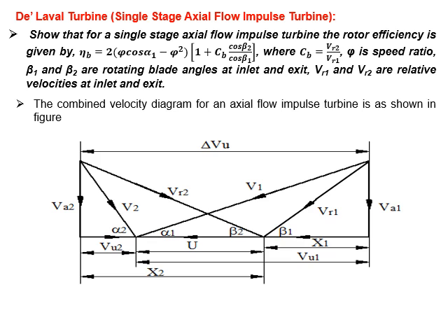In a similar manner, for the expression for VU1, the tangential velocity at inlet, VU1 can be termed using cos alpha 1. The cos alpha 1 is equal to VU1 by V1. For that reason, VU1 is equal to V1 cos alpha 1. In a similar manner, VU2 is taken as cos alpha 2 equal to VU2 by V2. For that reason, VU2 is equal to V2 cos alpha 2. So these relations are used in order to derive the expression for the blade efficiency.